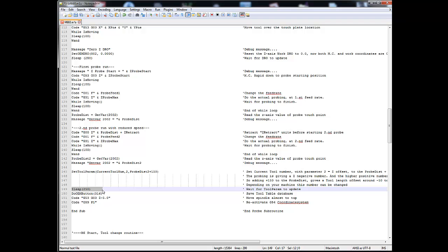Wait for the tool parameter to update. Then I found by mistake that it didn't actually update the tool table database. You need to save it also, and the do OEM button 316 does precisely that. So you'll need to make a call and save the tool table. I actually thought the set tool param did that, but it only updates it and then you need to save it.